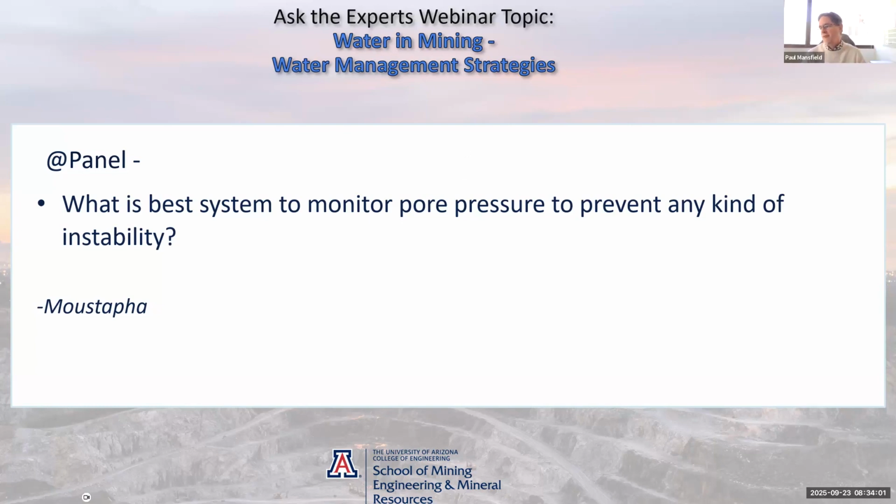Thank you. Okay, thanks, Gillian. Yeah, well, one of the best ways to monitor pore pressure is through the installation of vibrating wire piezometers in and around the pit. One of the great benefits of vibrating wire piezometers is that they enable you to install multiple sensors in the same hole, so you can monitor across fault structures which may be controlling pore pressures within the pit and causing local instabilities due to the hydraulic barrier effect that those structures might be causing.